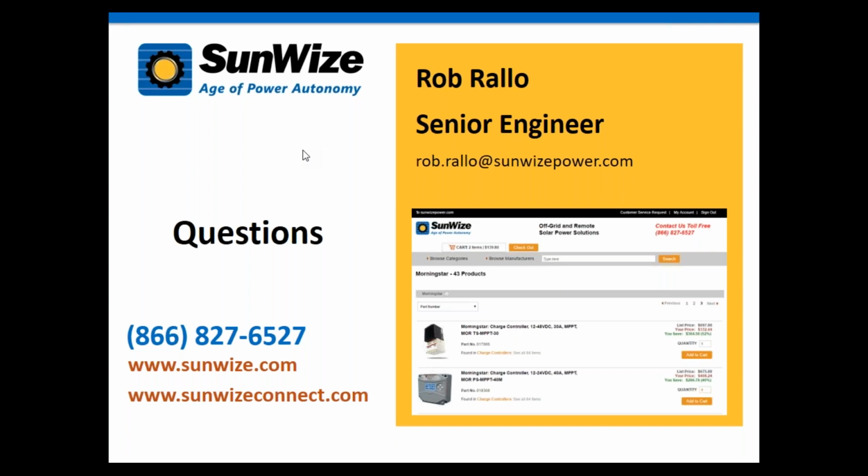Thanks, Rob. Appreciate it. One more thing on that. Also be careful with these devices as well. Some converters might have a tighter tolerance than other ones. Some of them might be plus or minus a volt. Some might be plus or minus a tenth of a volt. So just make certain that you're using the correct converter based upon your load requirements as well.